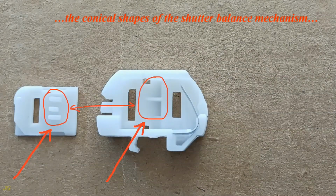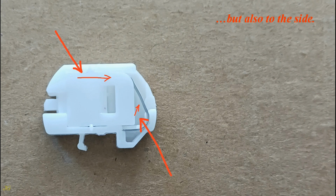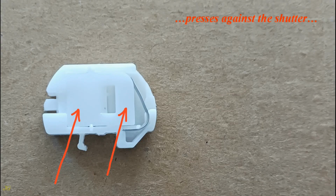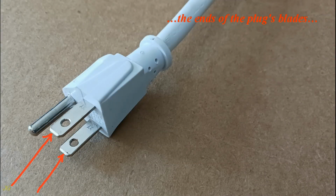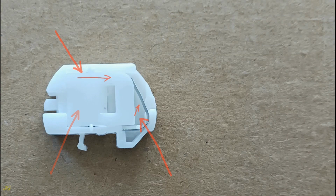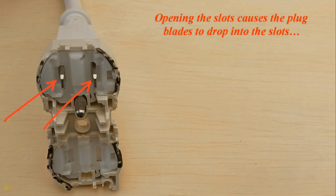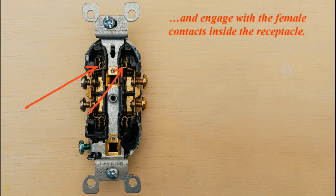The conical shapes of the shutter balance mechanism cause the shutter to slide not only inwards, but also to the side, as the plug presses against the shutter and moves it in and to the side. The ends of the plug's blades slide across the flat surface of the shutter until the shutter moves enough to open the slots. Opening the slots causes the plug blades to drop into the slots and engage with the female contacts inside the